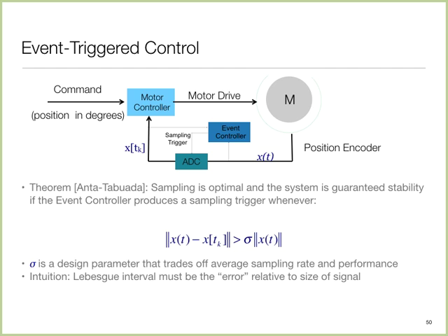Well, what I'm saying is the following: doing this requires continually solving this equation, which means you need an analog circuit which can do subtraction. You also need to do an absolute function, and then you can do a comparison. Comparison is again easy, but you're going to have some circuit sitting there burning power all the time. So if your goal behind all of this was to save power, then whatever you are saving on sample collection, you are losing on more complicated analog circuitry.